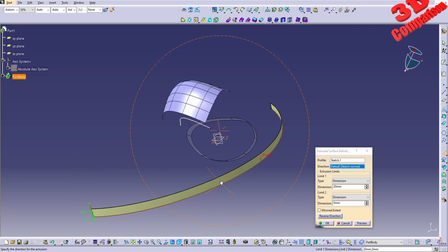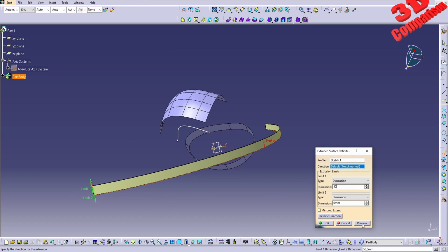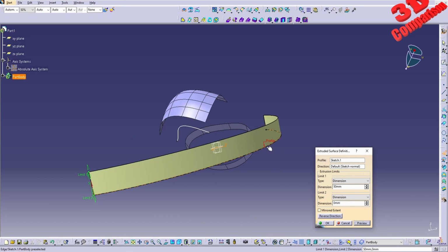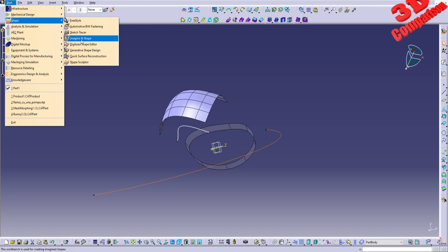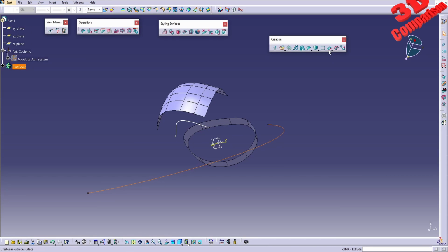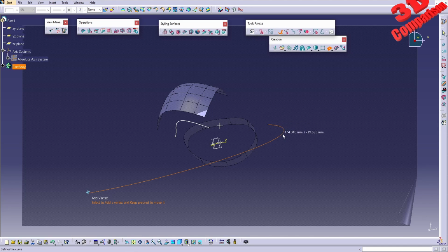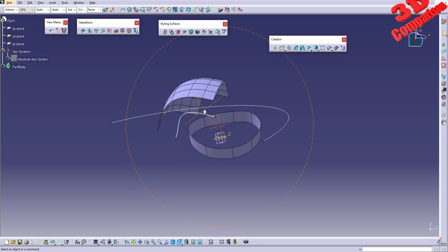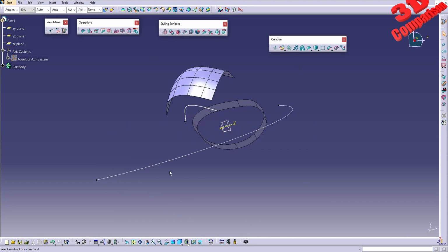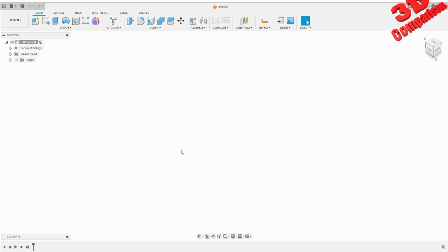So this will just be that fill surface, which is not editable. It is editable, but not within the freeform modeling. In order to edit this, I need to go within the sketch and change the base sketch that was used to define this. And if I try with the same sketch to go back to Imagine & Shape and try to extrude this, we're going to see that again, we cannot use that as an extrusion. And this is the most important comparison and difference within Fusion. Let's jump into Fusion and see exactly how we can work with extruded freeforms.